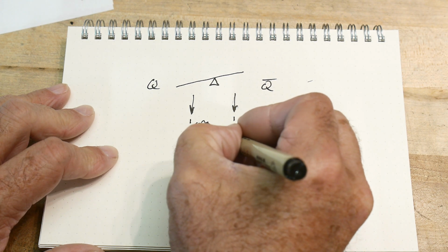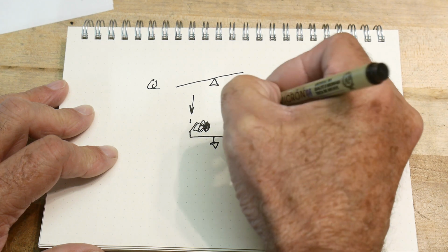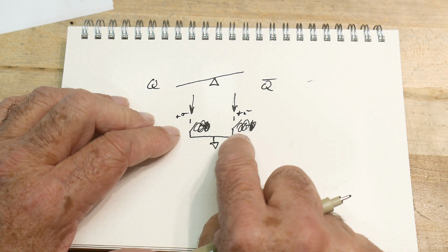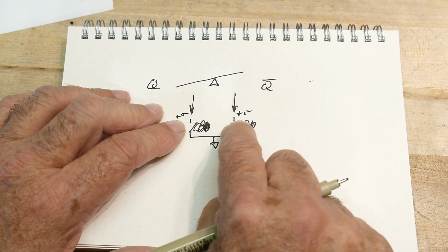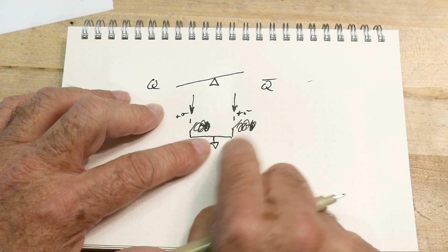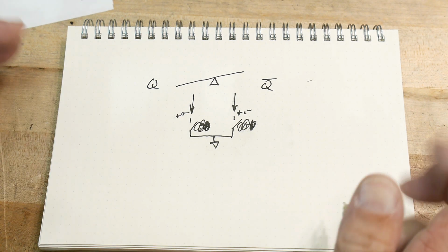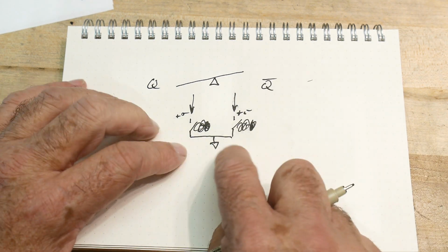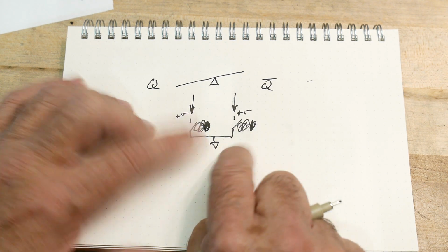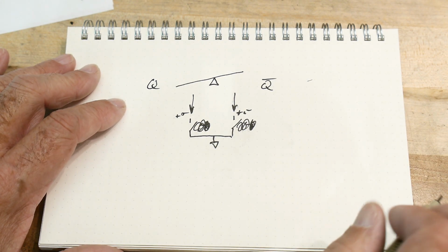And these switches would have to go to ground, right? And the top part of the switch, let's say, goes to +5. Okay, so that's the way these work. If they're switched, they're ground. If they're unswitched, they're 5 volts. Okay, so that's the way that these switches work, right? You tie them to ground, or you could tie them to +5, right? You could make it so that when you close them, they go high, and when you open them, they go low. Just depends on how the circuitry you want this to be, right?